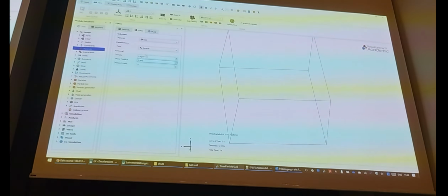Again, double click bulk, again 2500, a good value to start with. Shear modulus, let's stick with 10, it's also a good value, very fast. The lower the faster, by the way. I can show you in a minute. And for steel, again 7850, doesn't make a difference because it's rigid anyway. Shear modulus, again 10, Poisson ratio 0.3. And last material, plexi, I don't know, 5000 probably. It's rigid anyway. Shear modulus, again 10, and Poisson ratio 0.3. So we have more or less three very similar materials.